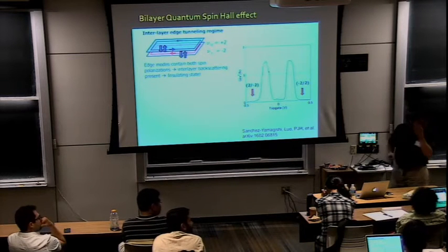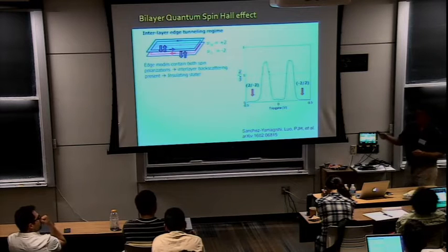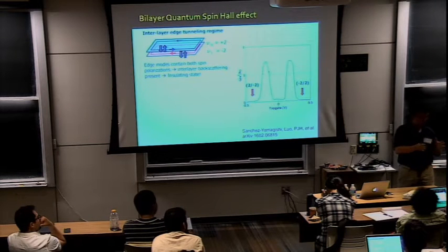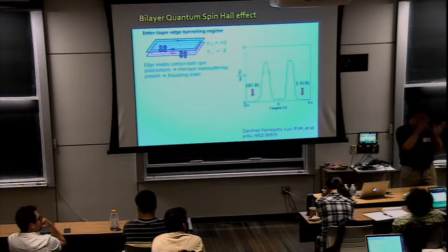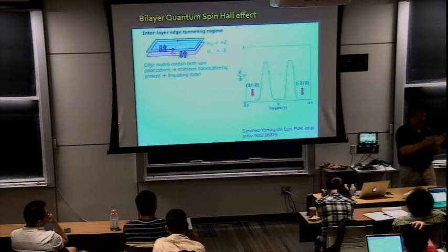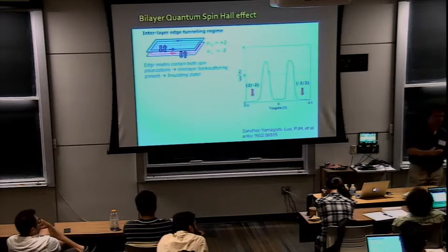Why did you etch the edges? It turns out that when you fabricate these devices, very often there are some irregularities, and you're trying to get an ultra flat, very clean area of the graphene. So for that you etch, so that you measure transport only in that, and you also have a rectangular geometry because it's more convenient, for example.